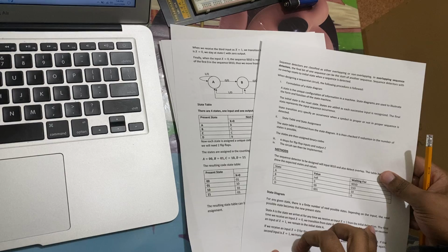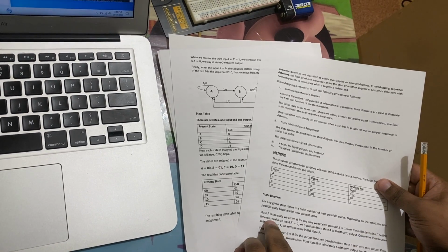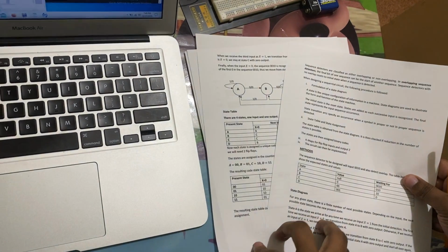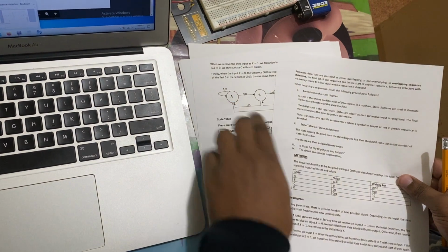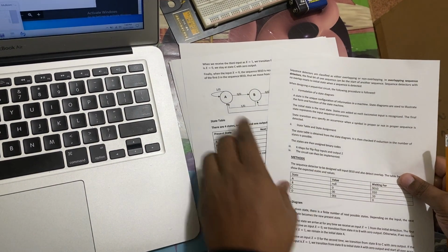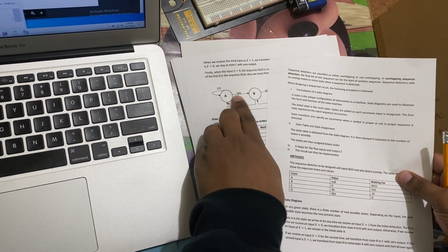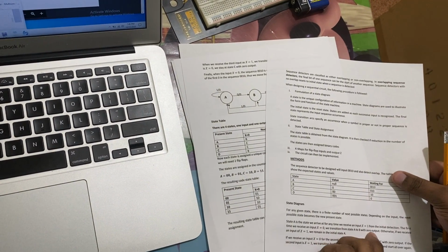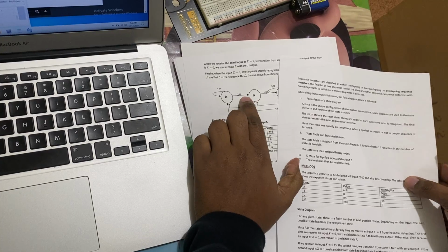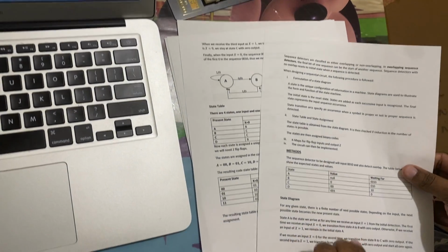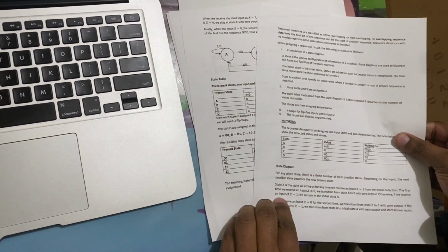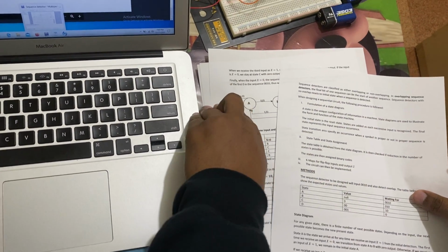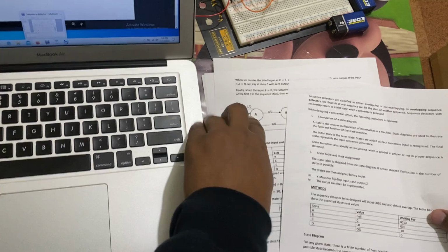From the initial state, the first time we receive an input X of 0, the transition moves to state B with 0 output, which goes here with 0. Otherwise, if the input X is 1, it remains at state A.